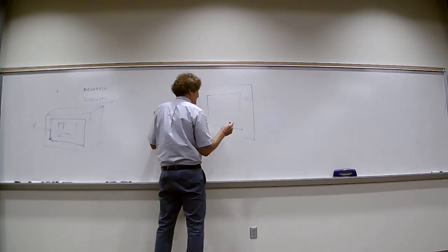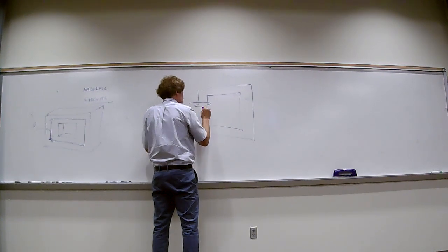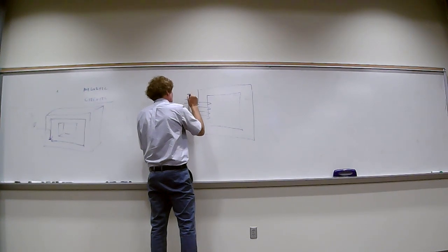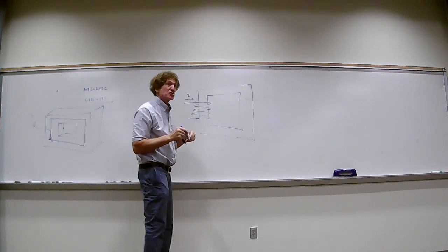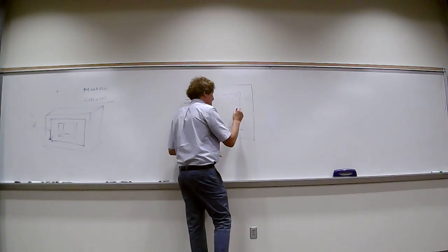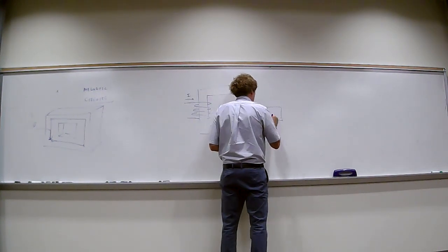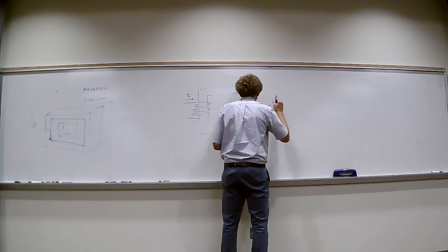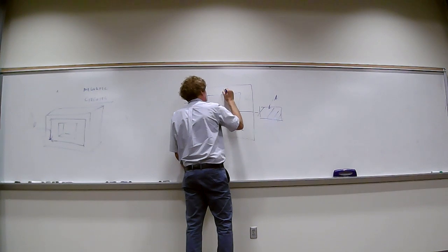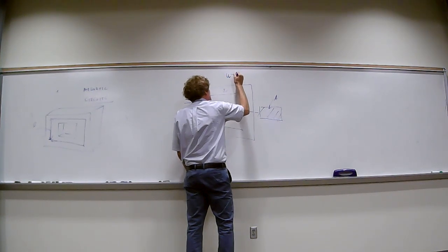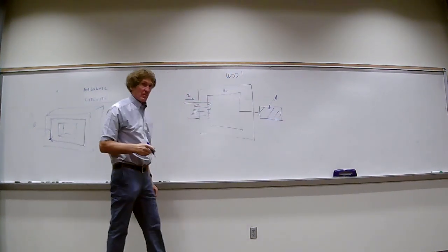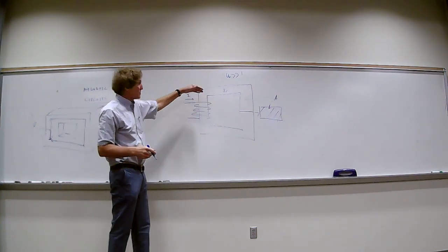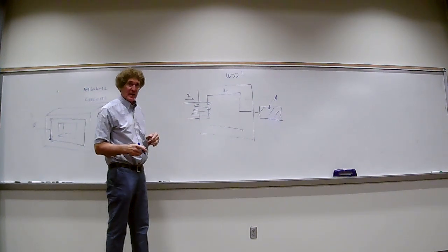So we're going to have something like this, and we're going to put turns on this, and we're going to have a current I flowing in it. I'm just showing you the problem. We're assuming this has a certain cross-sectional area A, and it has a certain permeability, mu relative. Now, mu relative generally is much greater than 1. What that means is all the magnetic flux we're talking about is assumed contained within it. There's no field fringing we have to worry about outside that area.